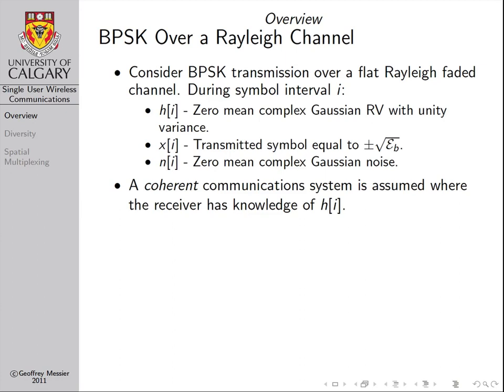Basically, through the transmission of a known sequence of symbols, either as some sort of training symbol sequence that comes at the start of an information packet, or perhaps as some sort of pilot signal that is transmitted in parallel with the information. Basically, the receiver uses that known sequence to estimate the channel and then uses it to help in the recovery of the transmitted information.